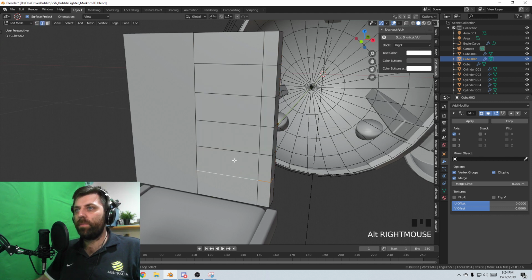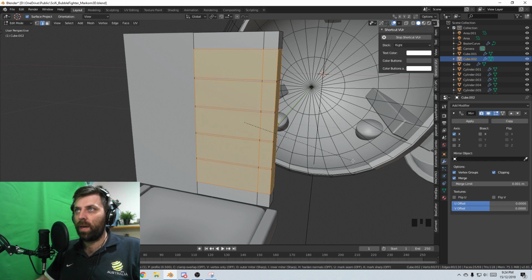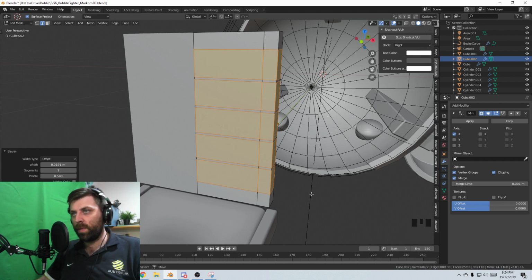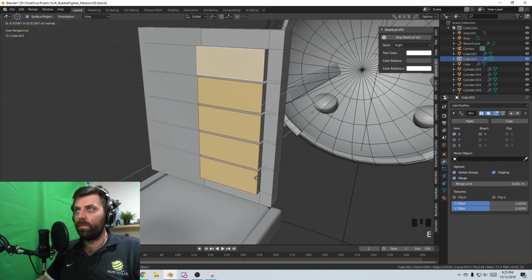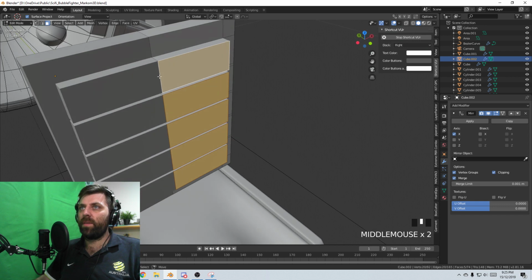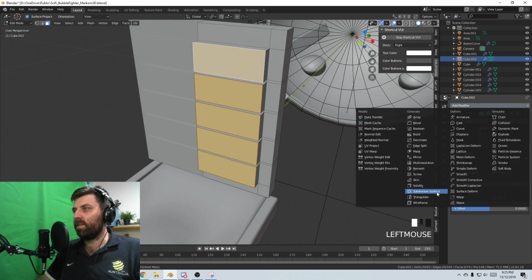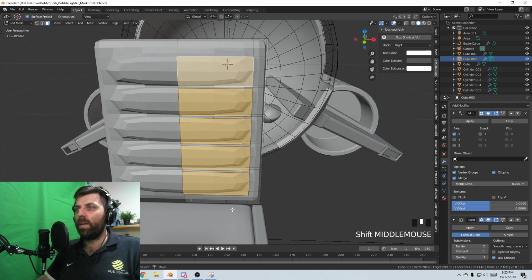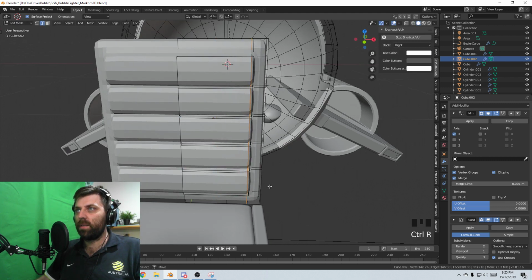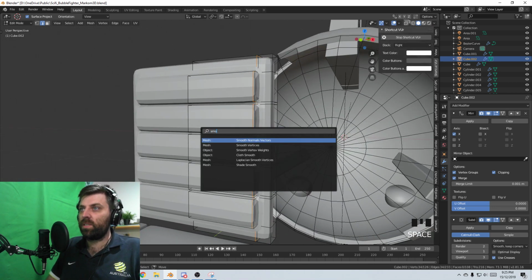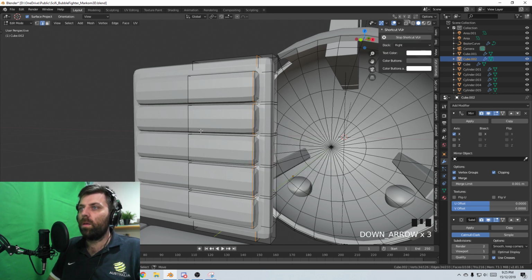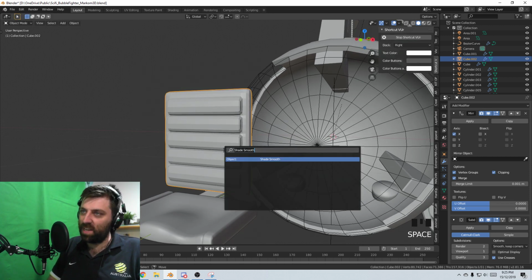Come into edge mode, and so Control B. These will be our bubbles that we were talking about just before. We're going to grab these faces. I'm going to E to extrude, and because we've turned on clipping, there's not going to be a face in here, which is good. Add modifier, subdivision surface. And now if I come in here and select it like so, put our edge loop in. Let's just go shade smooth. Or not. Now shade smooth.